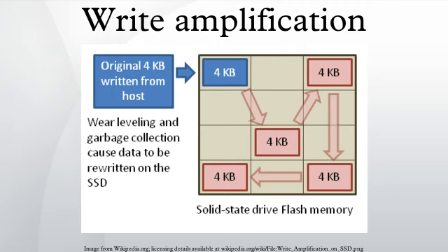Factors affecting the value. Many factors affect the write amplification of an SSD. The table below lists the primary factors and how they affect the write amplification. For factors that are variable, the table notes if it has a direct relationship or an inverse relationship. For example, as the amount of over-provisioning increases, the write amplification decreases. If the factor is a toggle function, then it has either a positive or negative relationship.